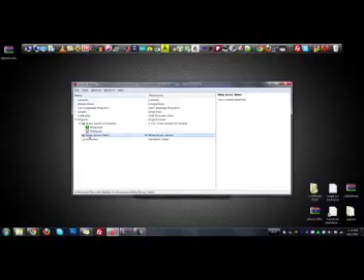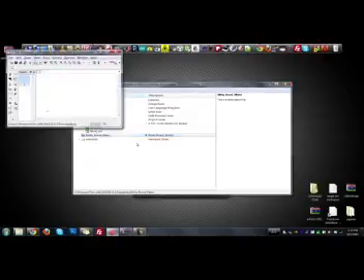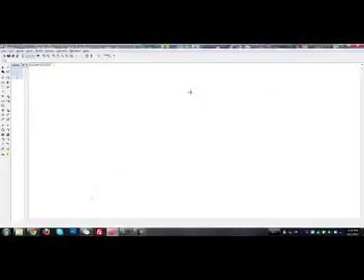So now that we've got that project, that's great. Within that project, the first thing we're going to do is make our schematic. So right-click on it, hit New Schematic, and the schematic window pops up. Maximize it, and we're ready to start adding components. I mentioned earlier that I wanted to use a battery clip holder that's supplied by Adafruit Industries. Luckily, Adafruit has an Eagle library that you can download from GitHub that has designs for basically most of the components that they sell. So I'll show you how to add an external library.